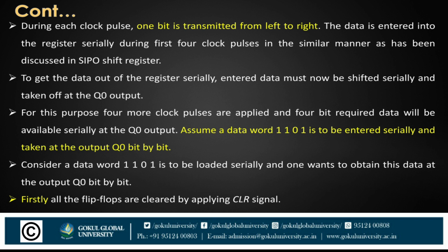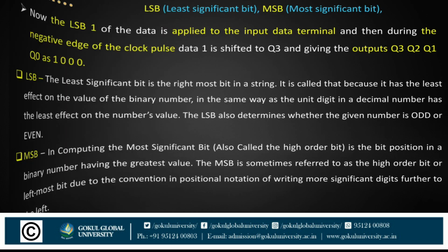Assume the data word 1101 is to be entered serially and taken at the output Q0 bit by bit. So consider that data 1101 is to be loaded serially, and we obtain this data at the output Q0. Firstly, all the flip-flops are cleared by applying the CLR signal.